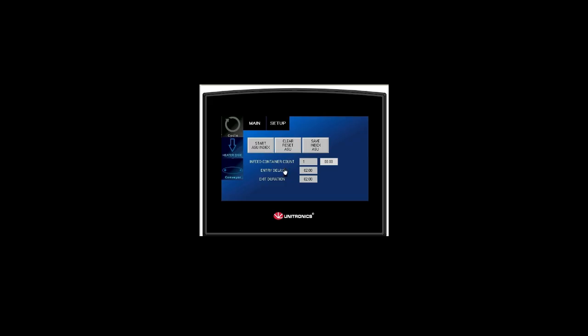I'm going to push containers up against my entry pin once I have all my mechanical adjustments made. Once I have enough containers up against my entry pin to fill the shrinking zone, which as standard is 1, then I'll have a couple containers prior to that, and I will hit the start ASU index. It'll pull the entry pin back, turn my conveyor on, and move the container forward. And then the entry pin will extend and the conveyor will shut off, and then it'll display a time under my duration. If all looked good, I'll hit the save index ASU button, and then I'm good to go.